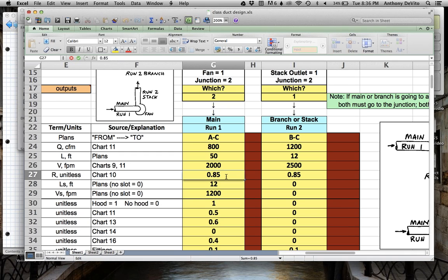Okay, so now what is R for the type of ductwork that we're using? Galvanized iron ductwork is 1. If we use flex duct, we look it up on which chart is that? Is that 10 or something like that? That is chart 10, roughness, right? So if we were using riveted steel at 2,000, it'd be around 2 or 2.1. If we were using flex duct at 2,000 feet per minute, it'd be 2.6 for the roughness factor. But for galvanized iron, that number is 1.